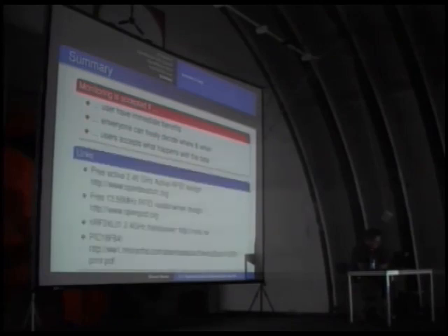Okay, here are some links. Basically, the OpenBeacon website. If you're interested in simple RFID, then it's openpcd.org. You can read and write MIFARE cards with this design. It's also based on the AT91SAM7 design, and Harald Welte implemented a very cool library set called librfid and libmrtd, which can be used to read out electronic travel documents by using our reader. This is the link to the NAF website and to the microcontroller.